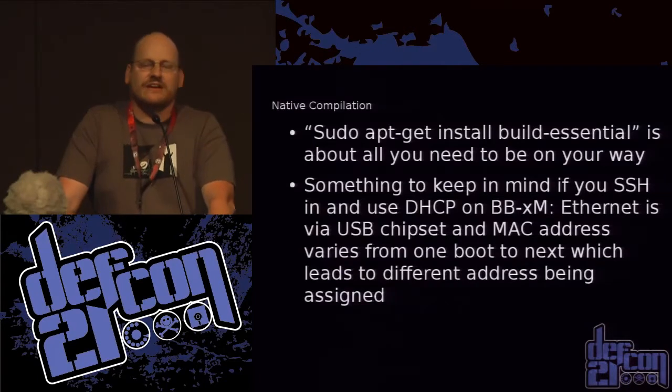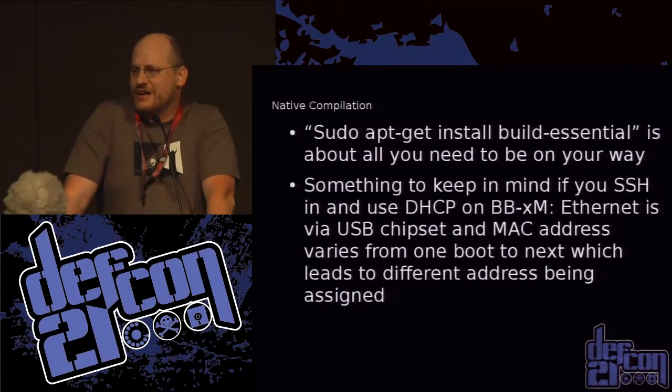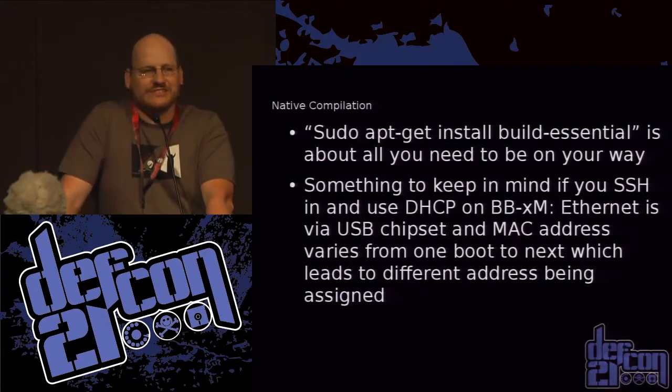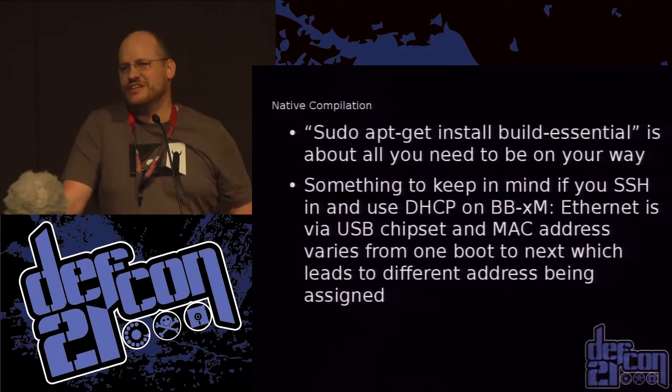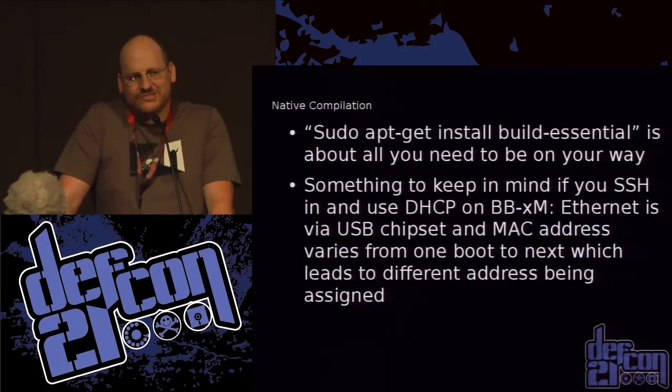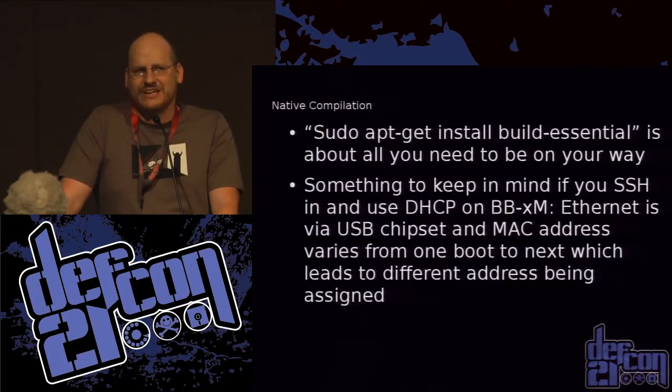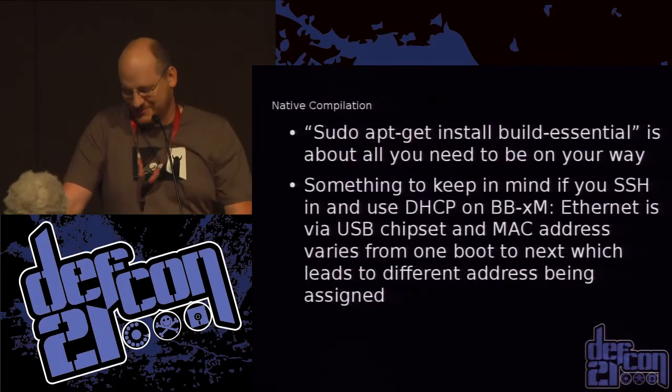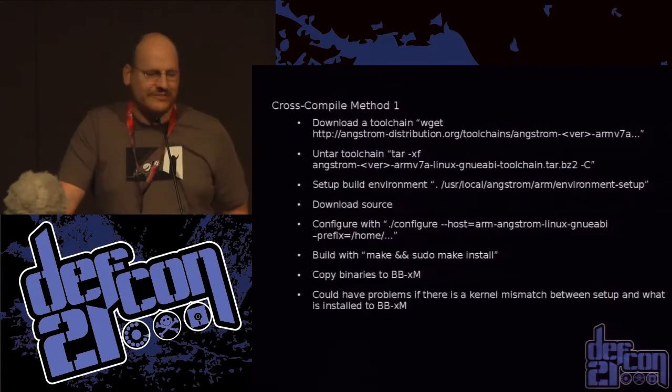Right? Something to keep in mind, if you happen to be using the Beagle board XM, be aware that if you're SSHing in there and you're using DHCP, every time you reboot the machine, it gives you a new MAC address, so you tend to get a new IP address. So if you're wondering, hey, why did that move yesterday? Well, just don't ever turn it off. You'll be fine.